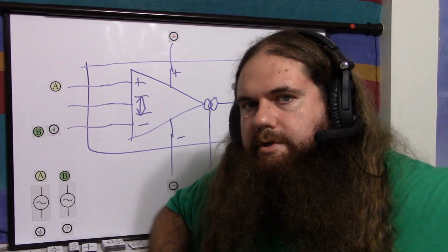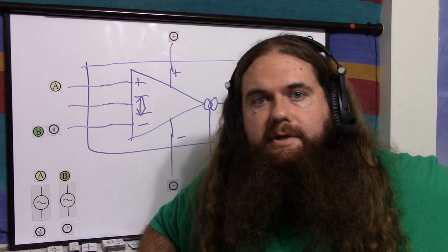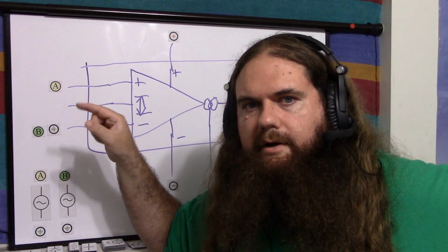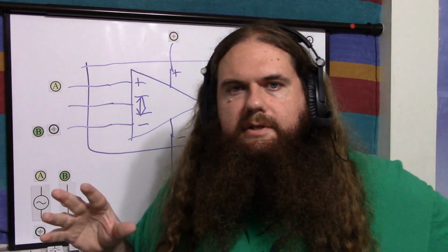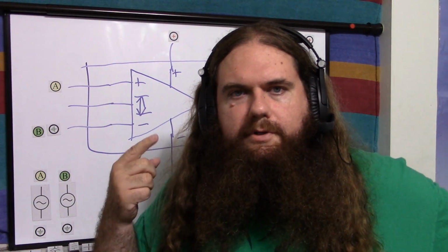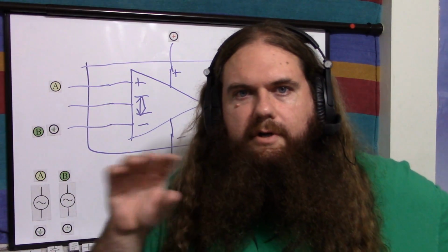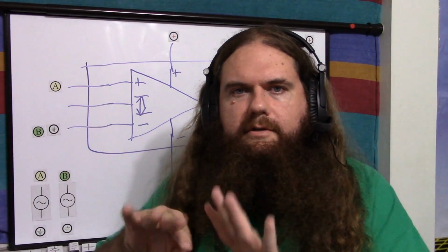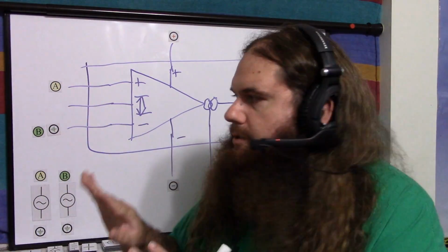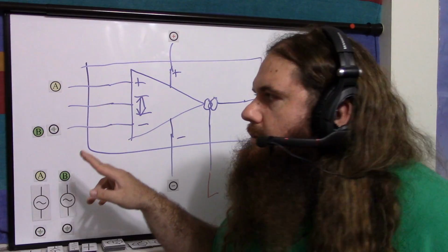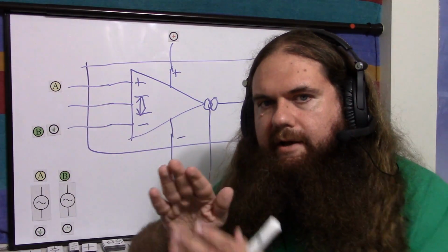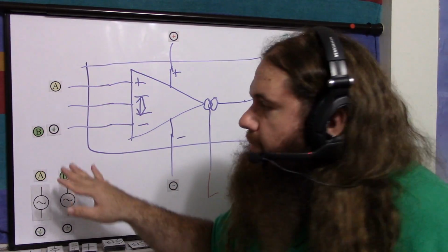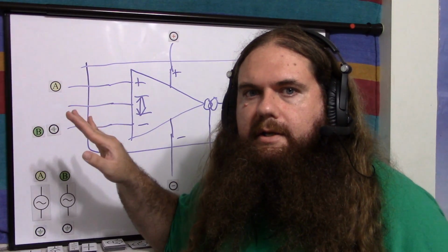Now, why wouldn't you just always use the smallest one possible? Because of noise. The smaller you make your signal with a voltage divider, the more susceptible it is to just noise in the circuit. And you can armor against that. You can put your bypass capacitors across your power to make sure there's no power supply ripple, and use all kinds of shielding, and there's a billion different ways that you can reduce noise, but there's still noise. So it's nice to be able to have the voltage be a little bigger and do all those anti-noise mechanisms to just get the absolute highest quality signal.